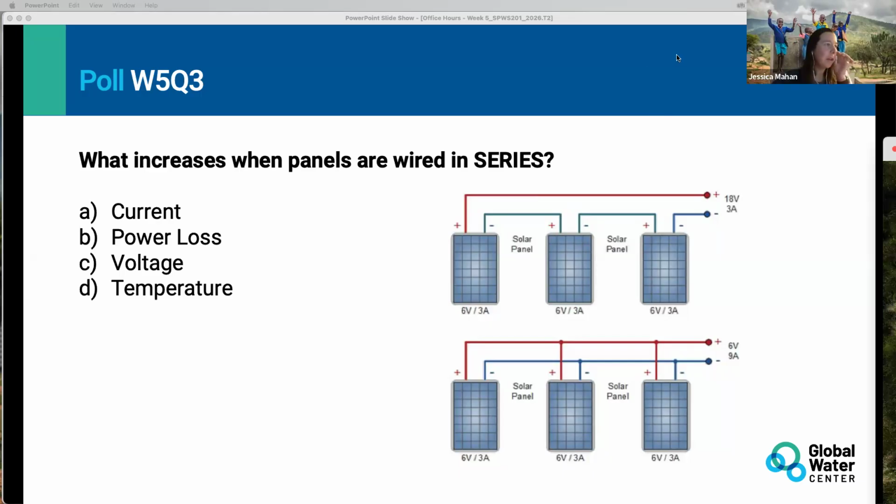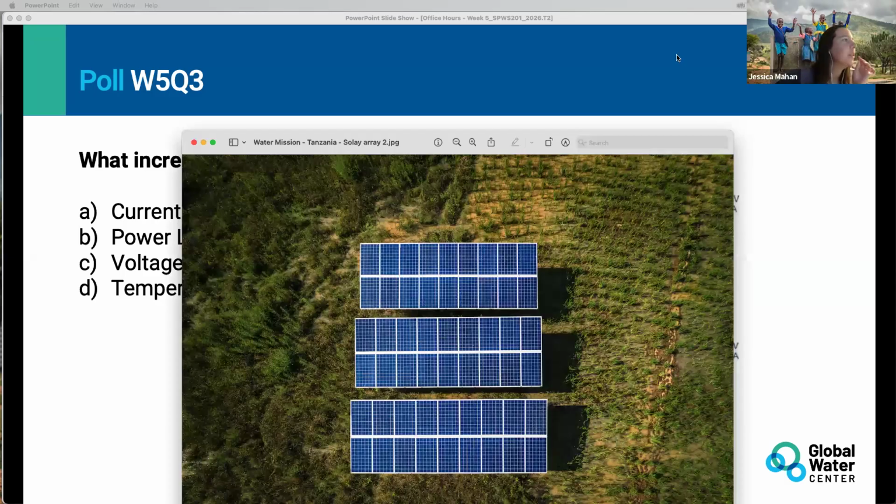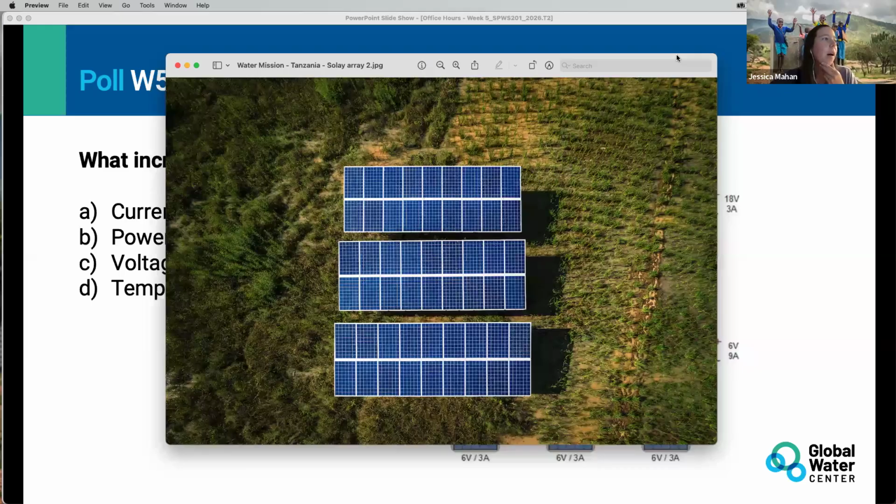So here's a fairly good one. You'll see they've got, I think, 9 panels across, and so 2 rows of 9 panels across. But they've just used multiple racks to get as many as they need. So my guess is they're likely using 6 parallel strings in this project, and each row would be its own string of in-series panels. And then they've got them all wired up underneath when they get into their combiner boxes, all wired correctly.